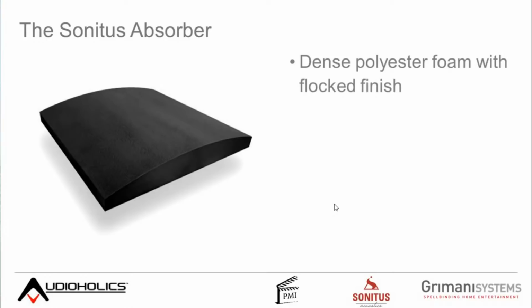It's a dense polyester foam. I didn't used to be a big believer in foams a few years ago because they tended to not work very well at low frequency. And then I found this vendor in Europe that makes this higher density polyester foam that works well down into lower frequencies. So this particular thing is a foam with a flocked finish that provides a little tympanic character at the front, which again gives it more low frequency performance.